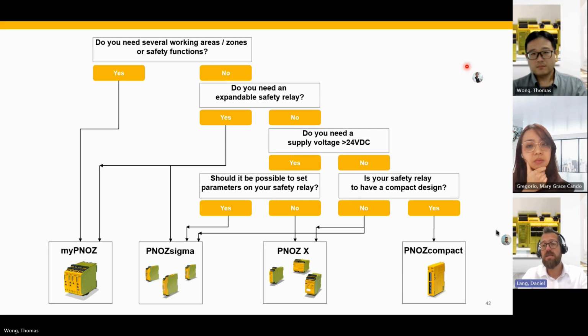Referring to relay and semiconductor outputs, in this case both are safe. Relays are a little bit faster, but you have to be aware that with the matter of time, because of all the energizing and de-energizing, this is a bit tricky, and let's say after 20 years or so, you have to change the safety relay. With semiconductor outputs, you do not have wear.